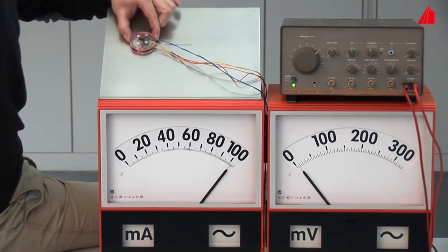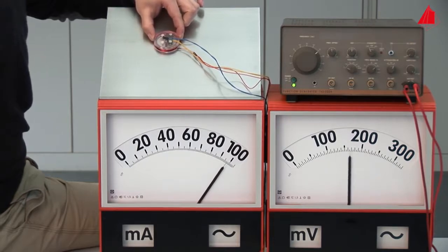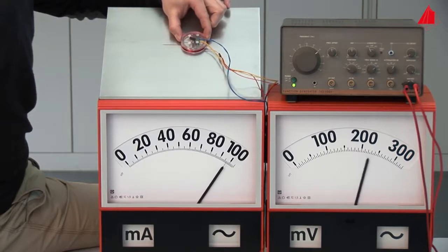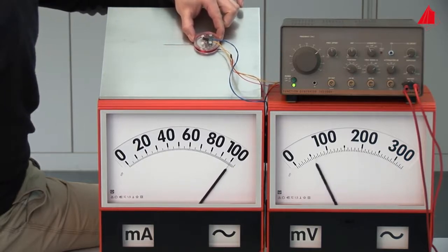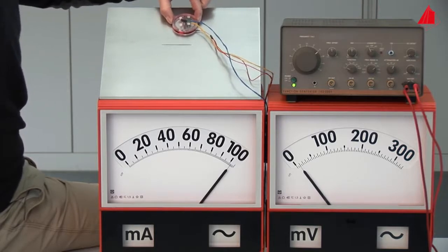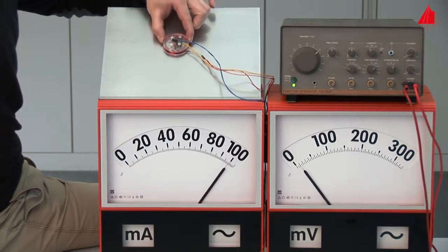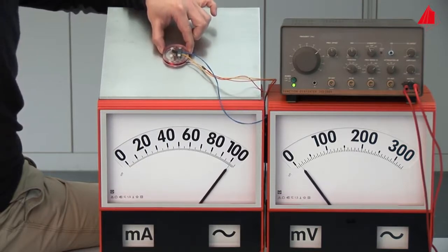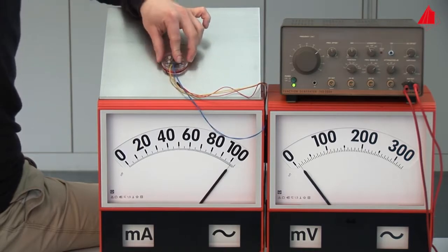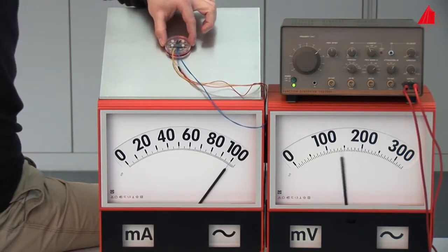Small voltage difference in the intact sheet, strong voltage fluctuations at the left side of the saw cut, and at the right side. But one point should always be kept in mind. The 2 D-shaped receiver coils must have the correct orientation for saw cuts and cracks. Otherwise you measure only little or nothing at all. If the orientation of cracks is not known, the probe is rotated by 90 degrees after the first pass and the test piece is scanned a second time.